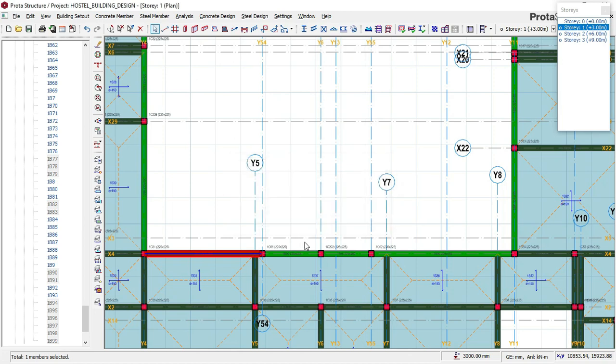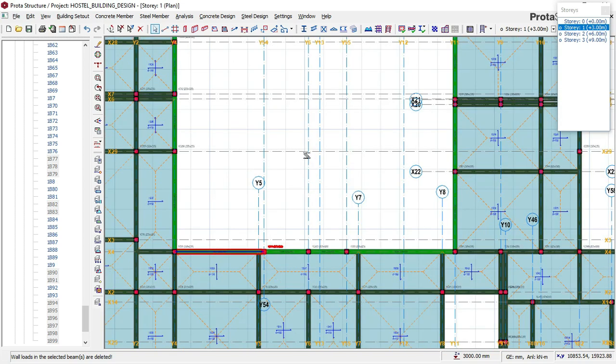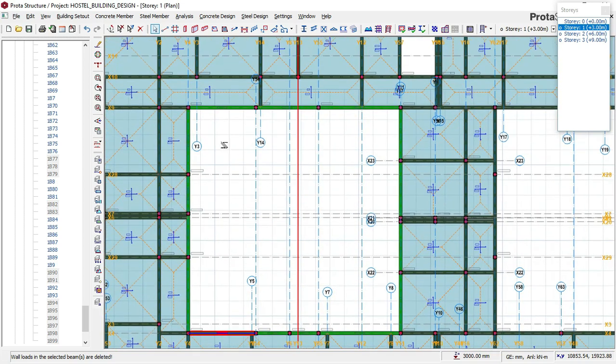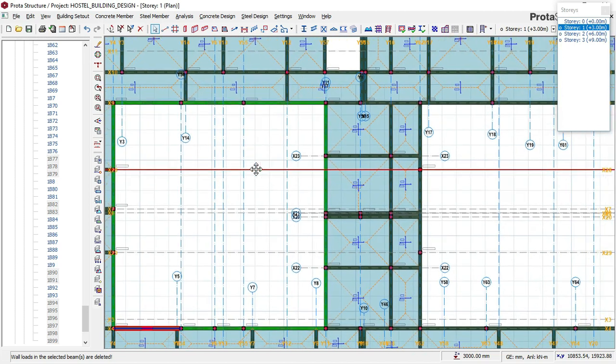Okay, so you can see that the beam right now around this perimeter has not changed color to light green than this deep one here. All the ones carrying this gray color on top have a wall load on it. So you can now see that all our perimeter beams in this area don't have wall load anymore.